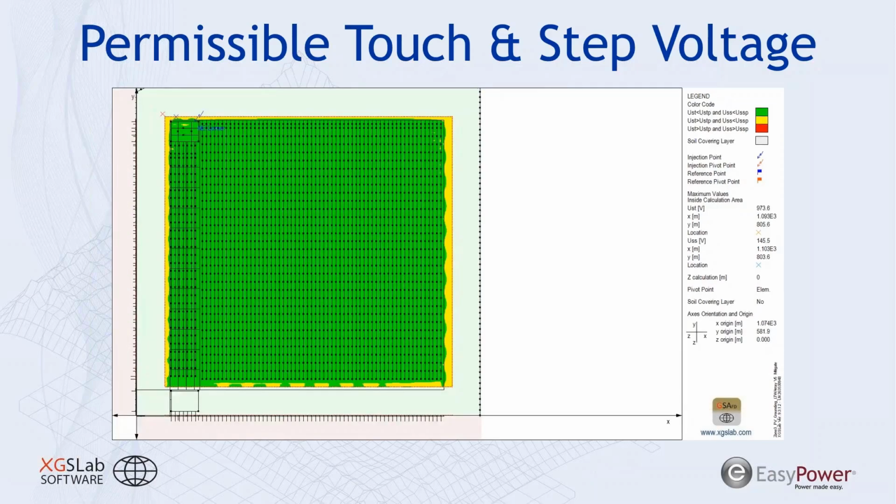In this situation, we need to add some additional grounding conductor in the northeast corner. So an additional conductor loop closing the open space on the right side here, and then a little bit tighter grid spacing on the left side here.